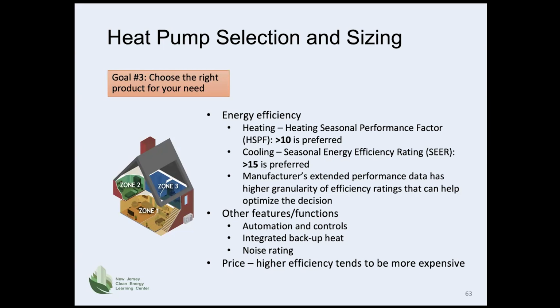As far as efficiency is concerned, today we don't really look at the EER per se, the energy efficiency ratio. It's more of a case of what is the efficiency of a particular unit over the course of a heating season for a particular climate zone. And what this does is it takes into consideration the bin weather data. So the overall efficiency for heating is rated on a seasonal basis.